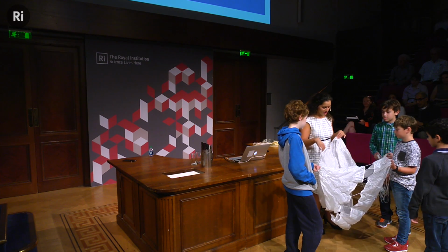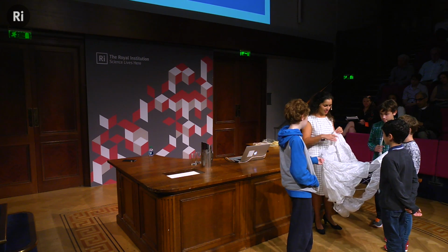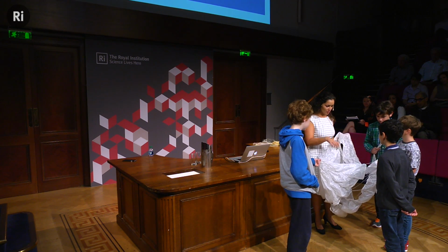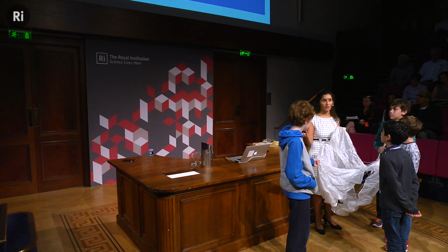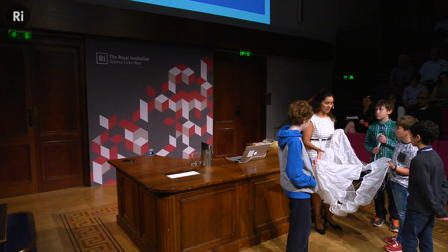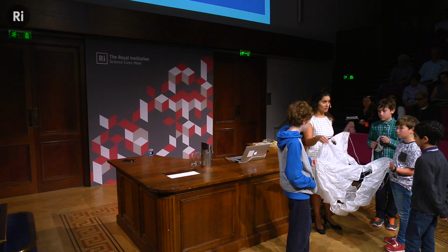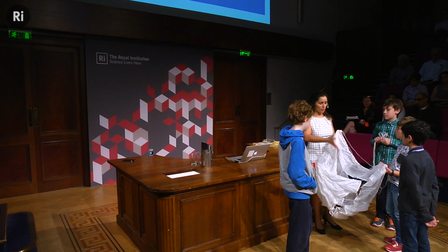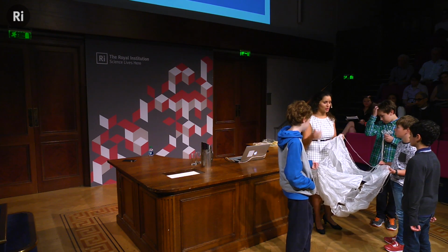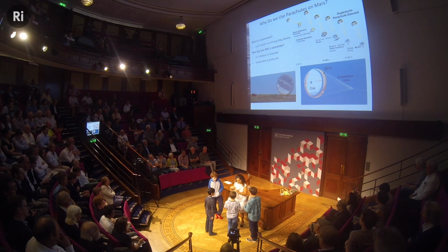And then what you also note here is that there's an opening here. So this is called a gap. This region at the top here is called the disc, and this is called the band. And so the reason why we have a very specific parachute design is because of the aerodynamic environment that we found ourselves in. It's actually a supersonic aerodynamic environment, and it gets really unstable. And the way you control the stability and the flow is by having this gap here, which allows the atmosphere to flow through it so it doesn't collapse too much. So I think I'll put this back, and then I'll let you touch this other thing since you're down here.